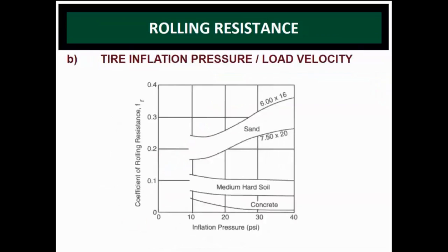And then next one is tire inflation pressure or load. Okay? So load is based on the material of the road. Okay? If concrete or medium hard soil or sand, so it has different rolling resistance and also inflation pressure.